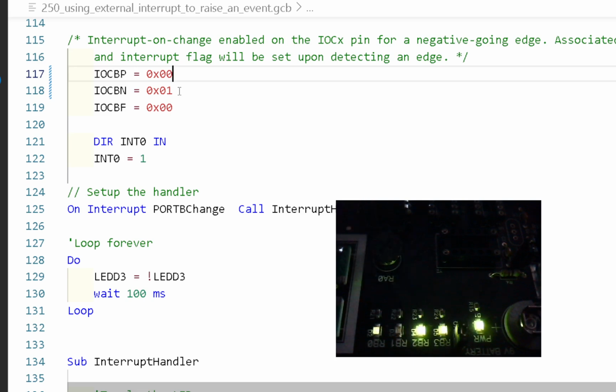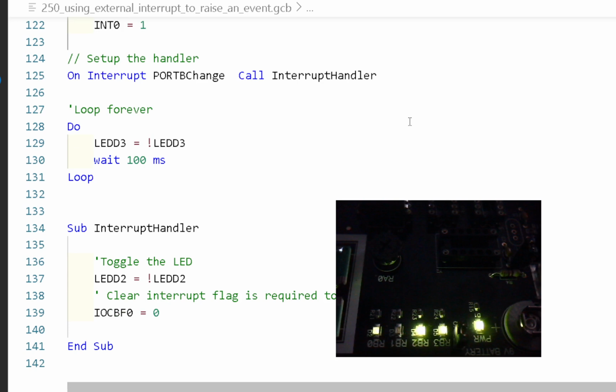So what happens if we actually set those both to 1? So what we're expecting, you never know the results. I didn't do this in testing. It's going to flash RB3 permanently on and off. I'm going to push the button, and you'll see when I push the button, because remember RB0. Oh no, it looks like it's following me, but it's been toggled by an interrupt. The interrupt is making it look like it's on and off with the switch, but it's not. It's all been done through the interrupt routine. I think that explains it quite well. I'm going to put that program back as it should be. I will check the documentation in the PowerPoint and make sure that's all updated.